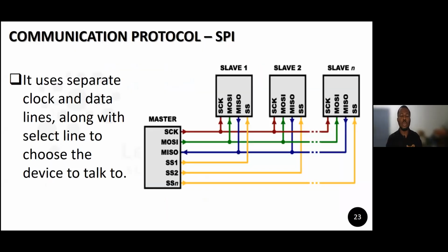All right. Then we also have the SPI communication. Now, the SPI is by far the fastest communication protocol on the Arduino board. All these 3 communication protocols that I've talked about also have their speed limit. SPI is the highest, followed by the I2C, and then UART is the slowest, okay? Now, whenever you use SPI, it also has a shared bus, all right? But it also comes with pin expenditure. First of all, you will need 3 pins to share. 1 pin for SCK, which we call the clock line. 1 pin for master out slave in, which is labeled as MOSI. Then we have master in slave out.